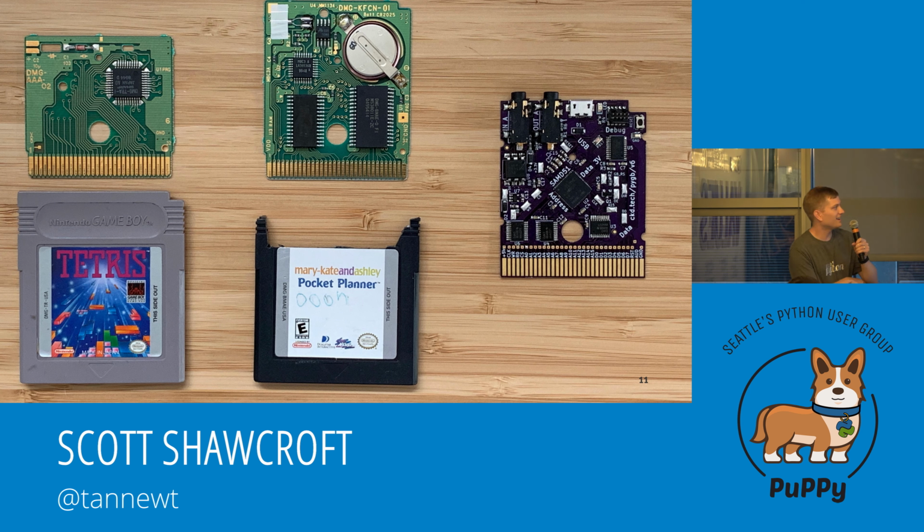The middle one is Mary-Kate and Ashley's Pocket Planner. As you can see, I cut cartridges open to make them fit my cartridge, so I go to the game store and get the cheapest Game Boy games I can, and this is one of them. But the card itself is actually pretty interesting for a couple of reasons. One, it keeps track of time, which is the crystal in the top left, taped down by a piece of tape. It has more memory, so the chip below that is allowing it to swap different memory regions in. And then it also has save state.